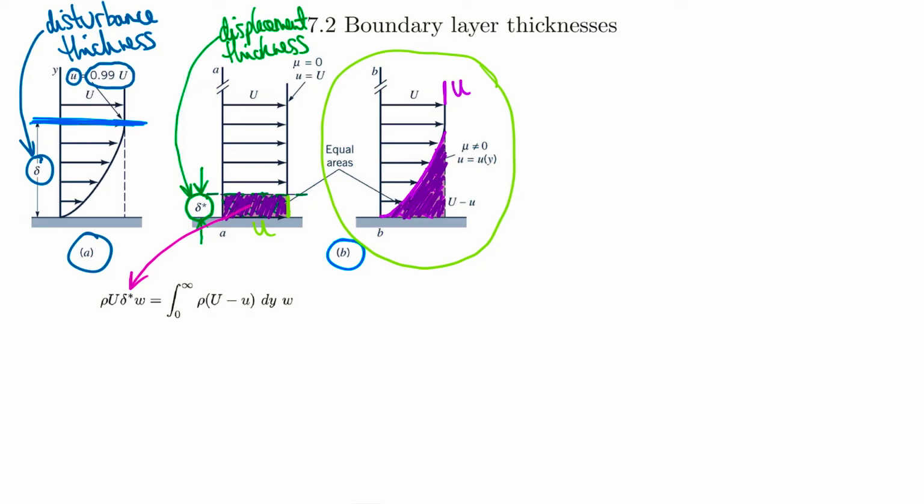We don't have to integrate in this case because there isn't a change in velocity over the area. So you end up with the density times the velocity, and then the area that's perpendicular to this flow. If you think of looking the same way the flow is traveling, it's going to be that height, delta star, times the width of the plate.